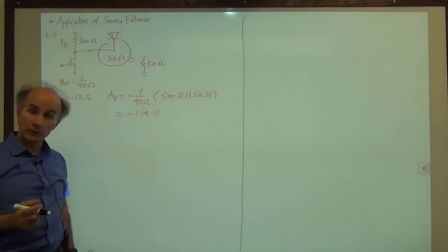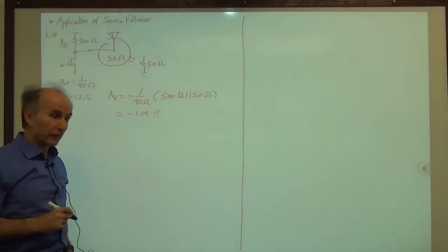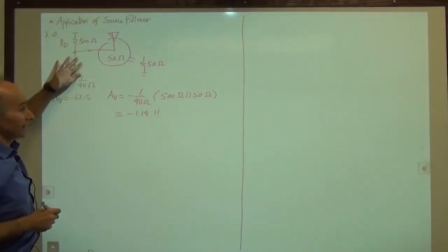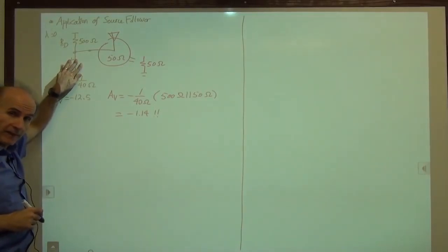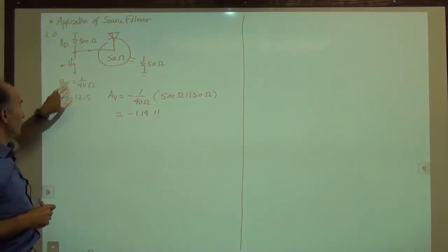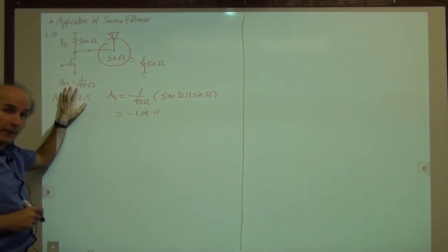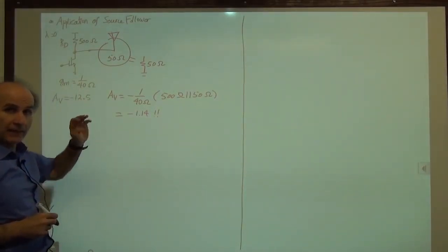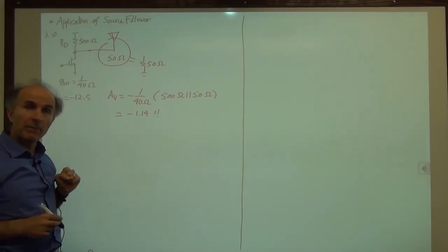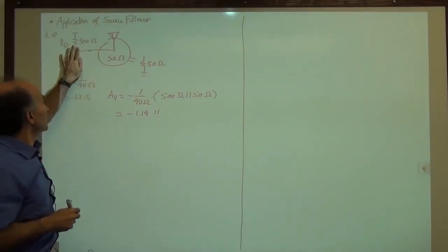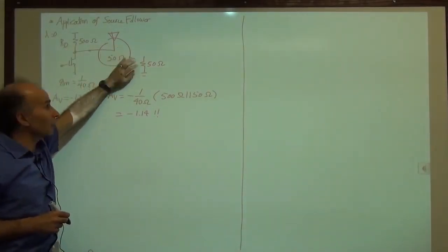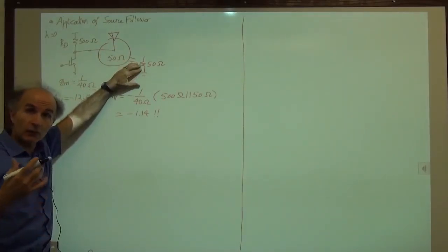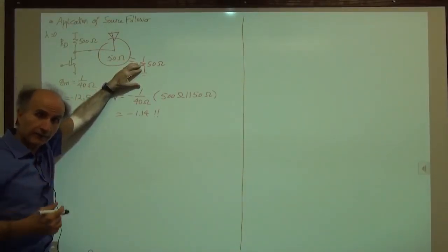Okay, so what do we do? Well, we can try to play with this circuit itself and maximize the gain. You know, we can try to push gm as much as we can. But a better approach, perhaps, is to try to place what we call a buffer between the stage and this load. This load is considered heavy, meaning that its value is low. It wants a lot of current.